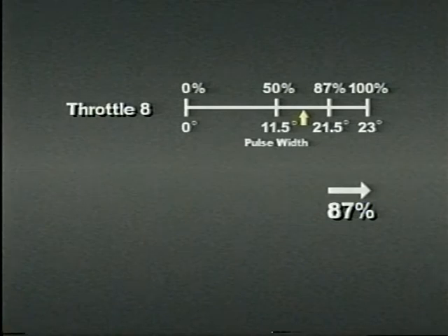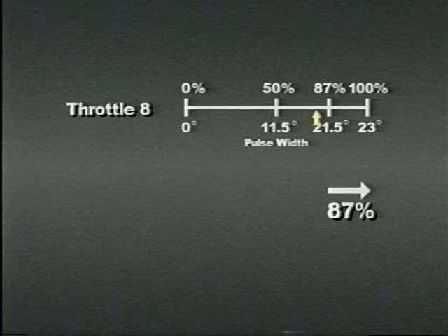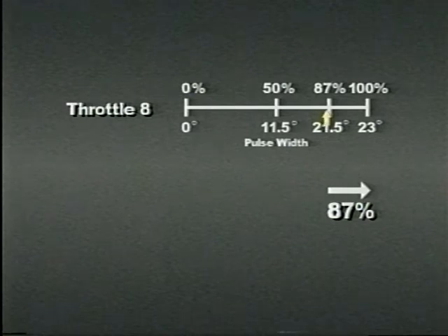If a problem develops on the engine or the load becomes too heavy, EMDEC will increase the pulse width to maintain engine speed. As the pulse width increases, the engine ratio signal also increases.